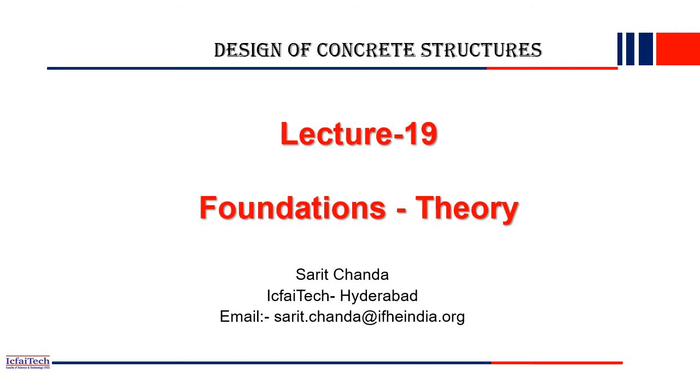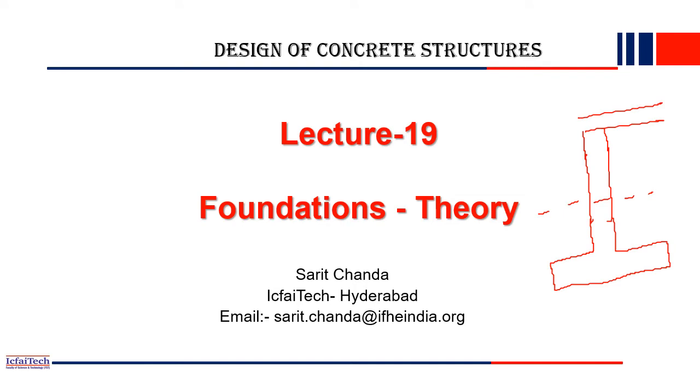So ideally, if you have a column, and this column goes down, and then you have the foundation at the bottom, right? So if this is the ground level, then above ground level you have beams, columns, all these things will be there, right? You have the beams, above the beam you have some slab, so many more things will be there. So this is our ground level. This top portion we call superstructure, and this portion we call substructure, right? And nearby are all the surrounding soils.